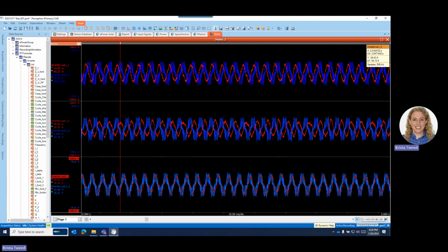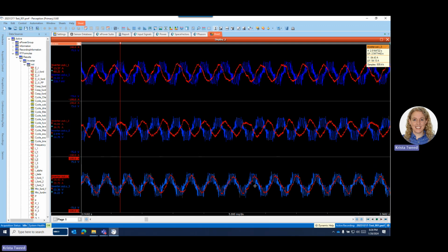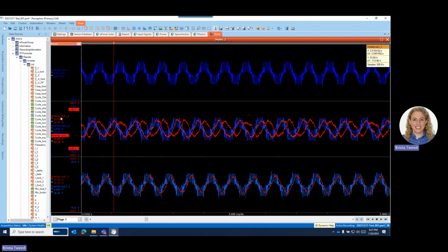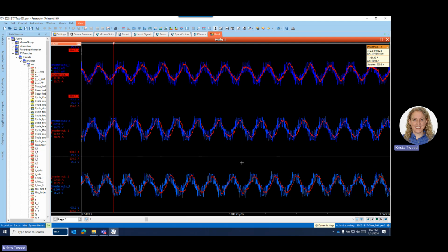And we've definitely got something funky going on here. You can see for U3 and I3 that the current, the peak of the red trace, is just a little bit ahead of the peak of the blue voltage trace. But on these other 2 phases, we've got a big difference. So you would expect it to be consistent between the 2. And if I look here, this peak in the red is pretty darn close to that peak in the blue. So I'm going to swap these 2 currents, move I1 down and I2 up. And now that looks like a much better match to me.